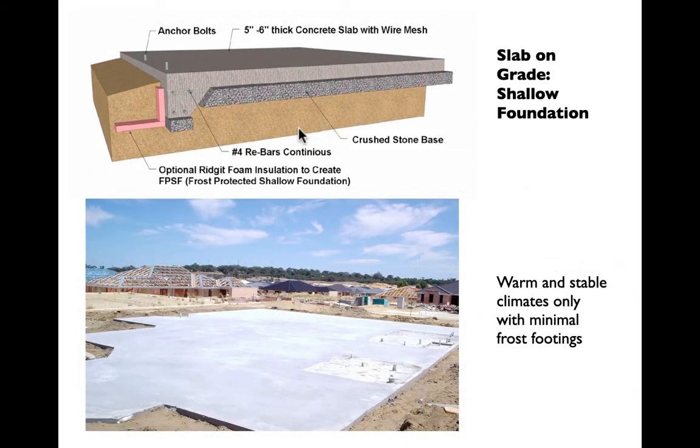So the simplest of these, again, is a slab on grade. If we are able to just basically take the live load, like in a house or maybe a big box store, what we'll typically do is excavate a little bit. We might go below the frost line, or we might insulate the soil so that we're using the heat of the building to keep the slab warm. And then by insulating it, that slab is going to radiate and warm the soil around it. It's going to prevent frost heaves from happening.